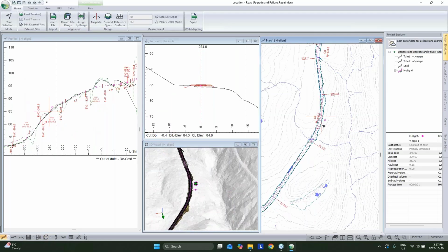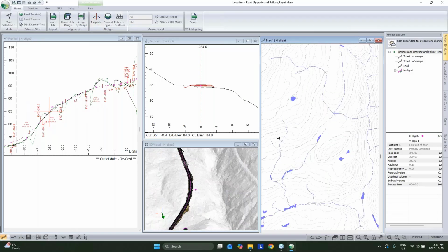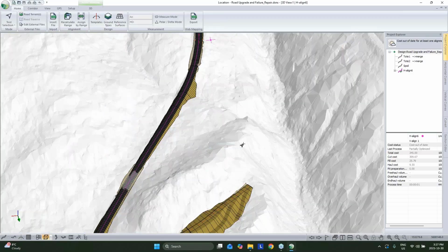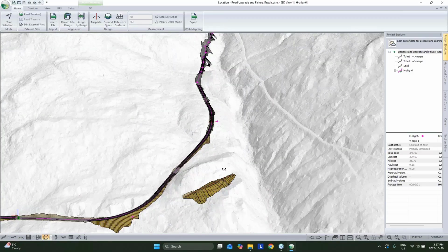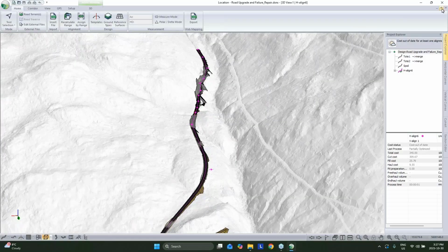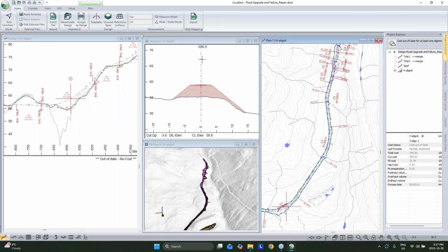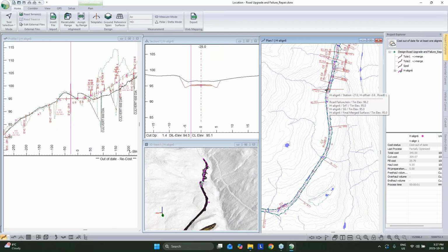But if we wanted to have something that's different than those templates that I introduced, and maybe we've got a little bit of variability in this resource road that we're looking at, but maybe from say here to there, I wanted to go with a wider road. Well, if I were to apply that, one, I'd check the station, and here, usually I have that at minus 586, and I'll go up to here and we'll assign that to minus 28.